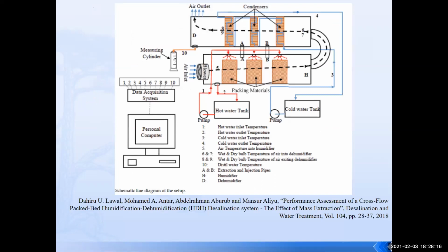Al-Munzir Isam has made experiments. His master thesis was an experiment on a cross-flow unit which is located on a truck. And then we had Abdurrahman Abrub in our lab, who came up with a unit having a cross-flow dehumidifier. So instead of a counter flow arrangement, it's a cross-flow arrangement, as you can see here. And we did the issue of balancing here. We had a paper talking about the effect of balancing that shows like a 25% improvement in the system performance.